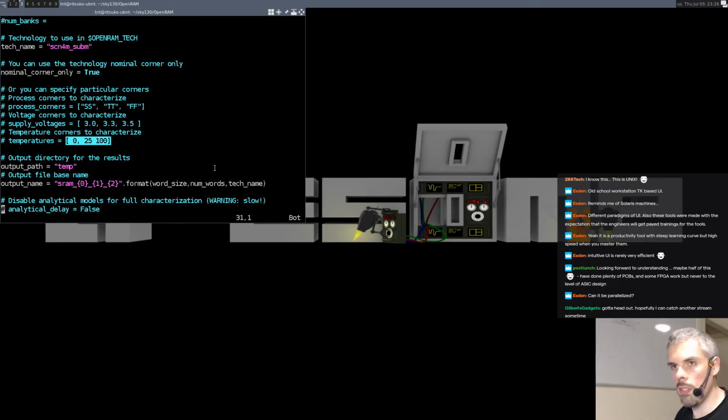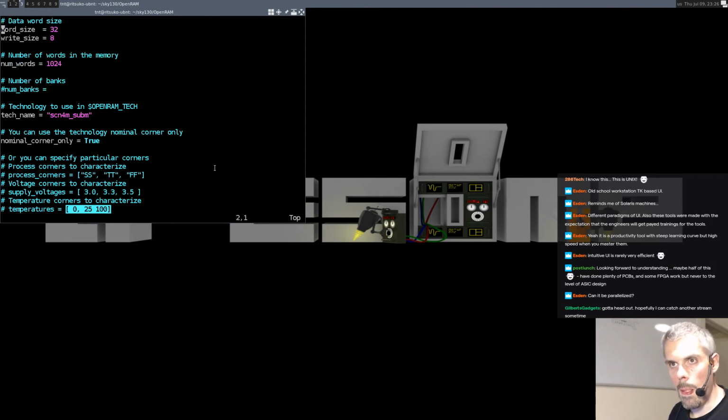So let's generate one of the RAMs here. At the moment, this does not support the Sky130 process. They have not yet published the required files, because to generate an SRAM, you can't use the standard cell library, since it does not contain SRAM cells. It does not contain some analog modules, like the sense amplifiers you find in an SRAM.